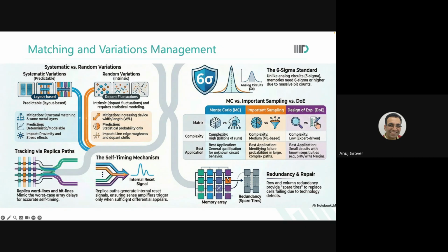Are we able to see this? See, unlike standard cells where we always left half DRC in every cell, किसी को कहीं भी लगा दो, doesn't make any difference. In memories, we do a lot of sharing across the boundary. Now, as soon as you change the boundary across which you want to share, you have to redesign everything and show that every sharing interface is clean. Are you able to see this? So as a designer now, you are putting double the effort in designing the compiler. Are you able to see this? This effort has immediately doubled.